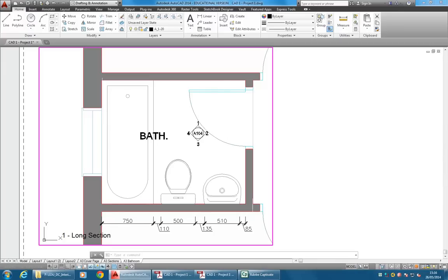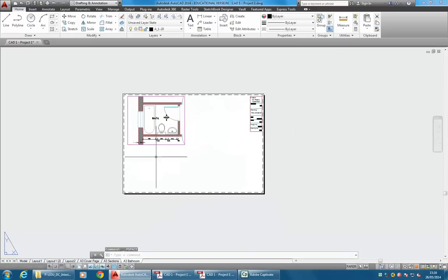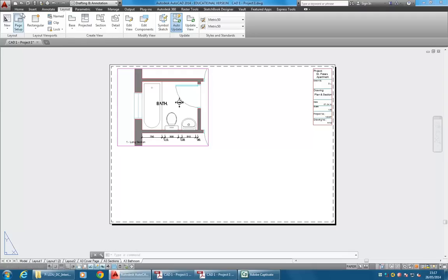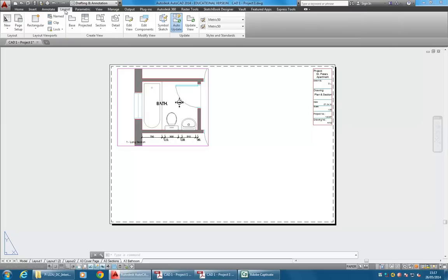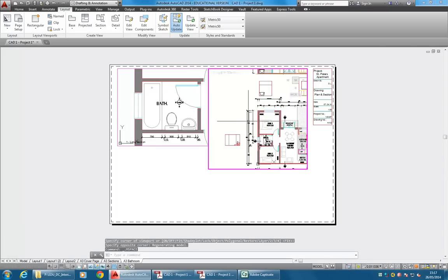And then the second viewport, so I've just gone back to paper, and I'm going to show you how to make a new viewport. Well, first I'm going to go to my viewport layer, and then on the Layout tab, Rectangular, and this rectangular again, and I'm just going to choose 2 points for my viewport and zoom in. Make sure you know about using the cube there, and that you should make a new viewport to get this cube.